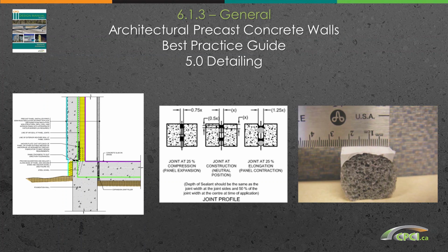Joints are required to accommodate changes in wall panel sizes and structural dimensions caused by changes in temperature, moisture content, and applied loads, while at the same time preventing water, air, and vapor penetration through the building envelope. Design criteria for joints include exterior exposure, considering the building orientation and climatic conditions; structural requirements, considering the amount of movement to be accommodated, for example, primary structure creep, interstory drift, building sway from seismic considerations, and thermal expansion and contraction effects of the panels and the structure; interior climate of the building; architectural appearance; function of the building; construction tolerances; and economics.